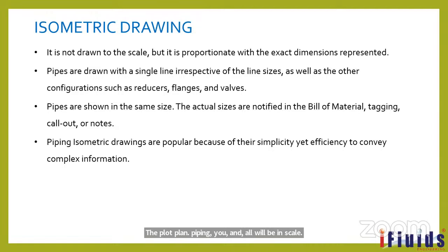If you put it into CAD format, a 2D drawing, you can measure the distance from one end to the other. Based on that, you can calculate how much distance there is between the equipment. So this pipeline will be 100 meters, this size of pipeline will be 10 meters. Like that, you can come to a conclusion and plan for that. Whereas the isometric drawing is the next stage.